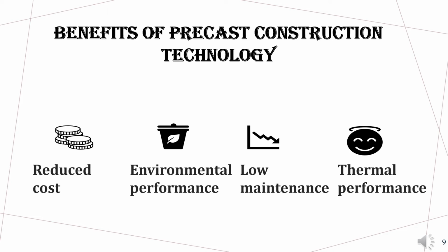Thermal performance. Expenses involved with heating and cooling can be substantially minimized by thermal mass advantages of concrete. Reduced peak heating and cooling loads can be accomplished since concrete responds slowly to outside changes in temperature.